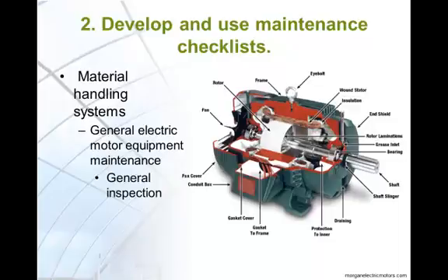A general inspection is a check for abnormal wear, vibration, noise, heating, damaged parts, or excessive power draw. The motor should be cleaned. The cables should be checked for good connection, and the mounting connection bolts should be tightened to the proper torque specifications. Specified parts must be lubricated with proper lubricants at the proper time intervals.